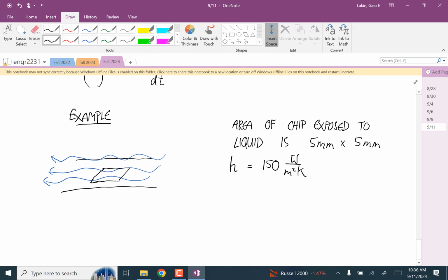And that's like specific to the silicone. Yes, and specific to the speed of liquid flowing, and specific to that liquid. So yeah, that has to be determined pretty much in exactly this. But if you're doing a ton of these, you can do that experiment and then use that value in the rest of your calculations for all the rest of them, you know. But yeah, you can't use other people's data on that unless it's a pretty identical situation.